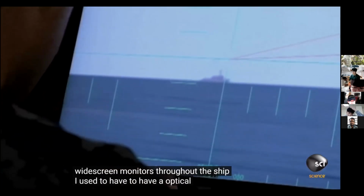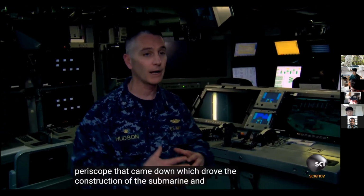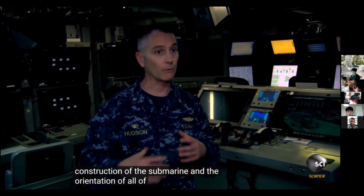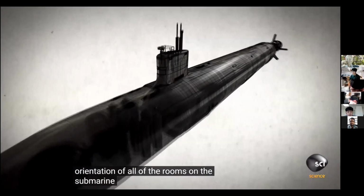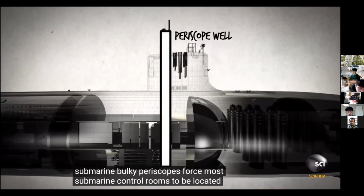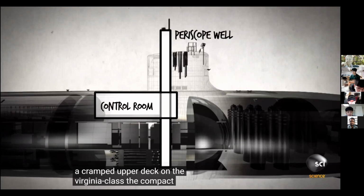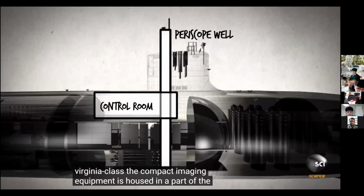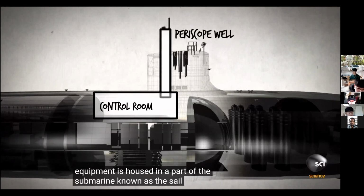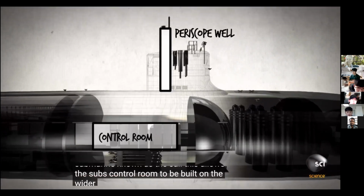I used to have an optical periscope that came down, which drove the construction of the submarine and the orientation of all of the rooms on the submarine. Bulky periscopes force most submarine control rooms to be located on a cramped upper deck. On the Virginia class, the compact imaging equipment is housed in a part of the submarine known as the sail. This allows the sub's control room to be built on the wider second deck.